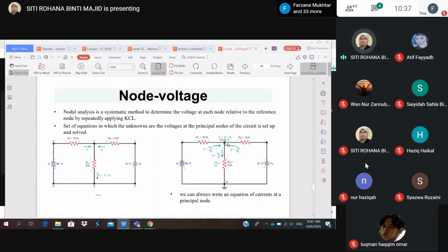Also for this node and the ground, the difference between the voltage at this point and this point, that means if you know the voltage, let's say V1 here at this particular end node, then V1 minus ground equals V1 over 6 ohm, because this is 6. And then another one is the voltage from here to here, and this current we designate as I2 equals VR2 over R2.